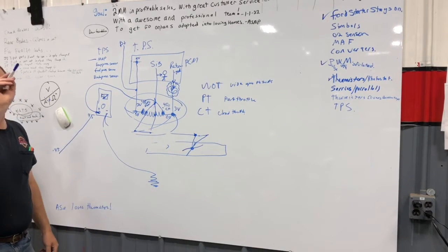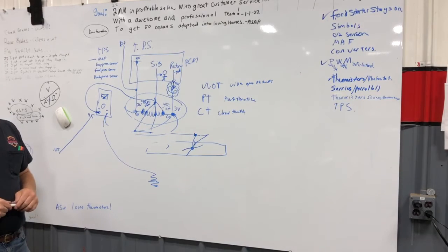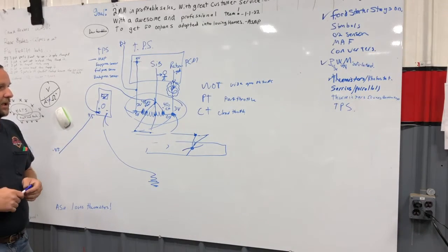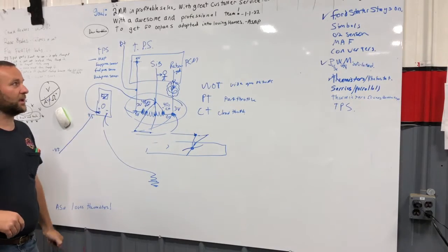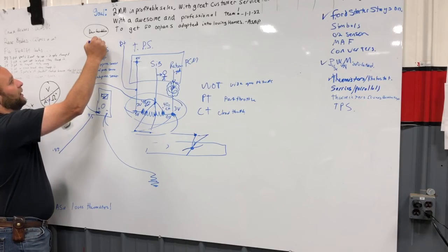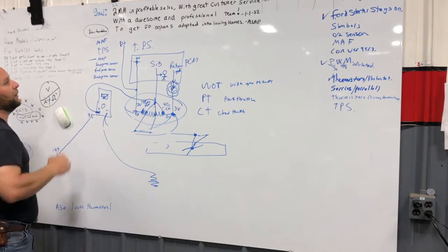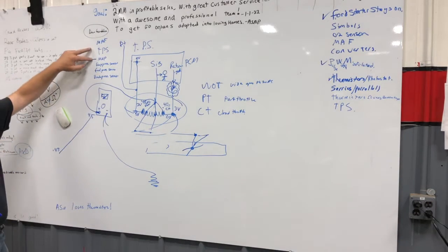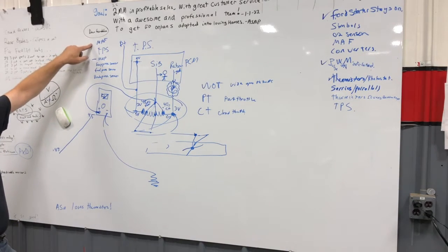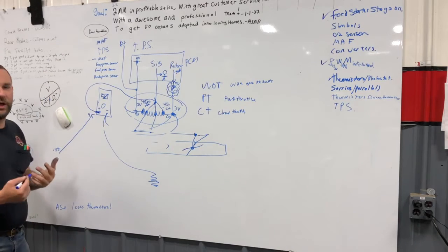On that car, if you unplug the mass airflow sensor, it would say, okay, I have no mass airflow sensor reading. I can't take that input data. He makes a decision, says, I'm going to look at TPS, I'm going to look at MAP, I'm not going to look at mass airflow. I'm going to run on the speed density system, these two. This is the mass airflow system. He makes decisions on the fly and changes stuff.